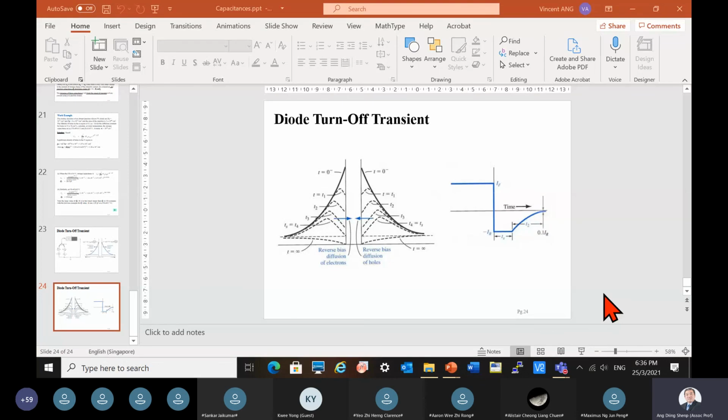But the moment forward bias is reached, where carrier injection happens across the junction, the further increase in the current will be controlled predominantly by the storage capacitance because this is much larger compared to the junction capacitance. Okay, I get that. Thanks.